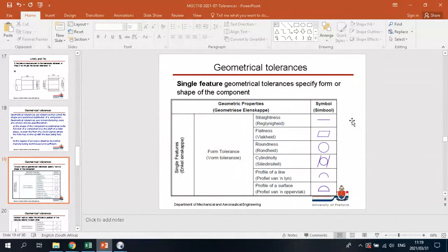You're going to use it to draw a line with your pen. So up to a 0.1 millimeter variation would still be quite fine. Flatness, if you have something like a flat mirror, then it would have to be quite flat, otherwise it will distort the image. Then you can specify a smaller number for the flatness.